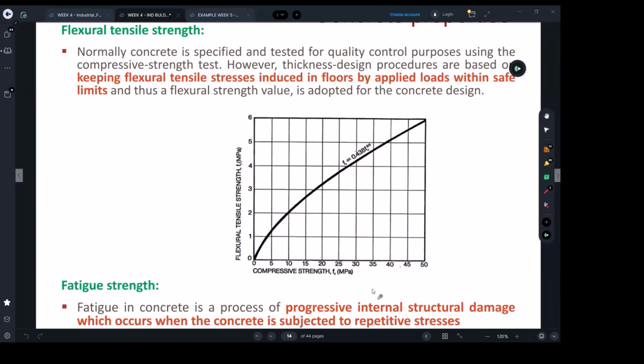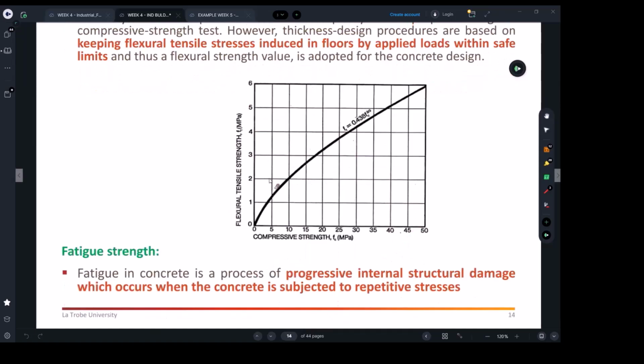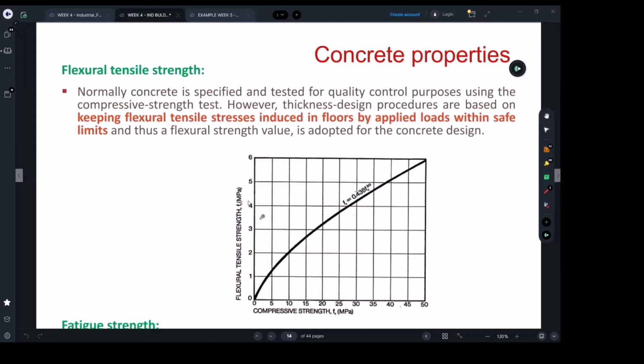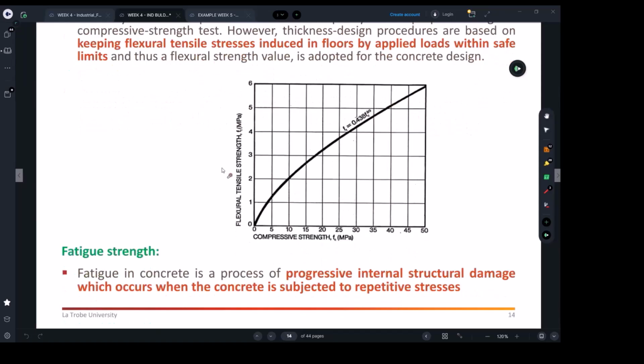The engineers will go through calculations for statics. They're going to find the flexure stresses from loads. If they go above 5 MPa, for example, like this, then they just have to put steel to deal with it. But this is just to let you know how the process is going to go. All right. Another thing the slabs can suffer from is fatigue. Fatigue really comes from dynamic loads, because those types of slabs are under forklifts, trucks, under impact.